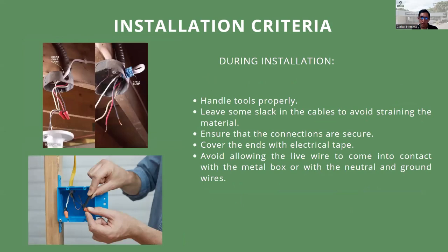here we have the tool installation. In this case, use the hand tools properly and leave some slack in the cables to avoid straining the material. Ensure that the connections are secure. Cover the ends with electrical tape. Avoid allowing the live wire to come into contact with the metal box or with the neutral and ground wires. Next.